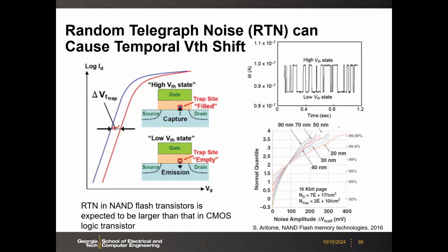So basically, you add temporal noise on top of your VTH distribution, right? Your VTH distribution already has spatial variation. On top of that, when you measure at different times, you may add additional noise. That means this distribution may become even wider. So that adds challenges, because you have these multi-level states, and you care about the margin or the gap in between.